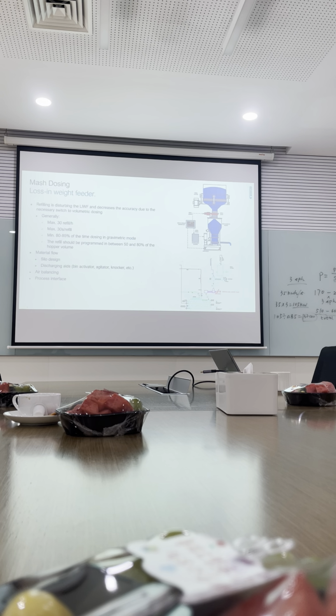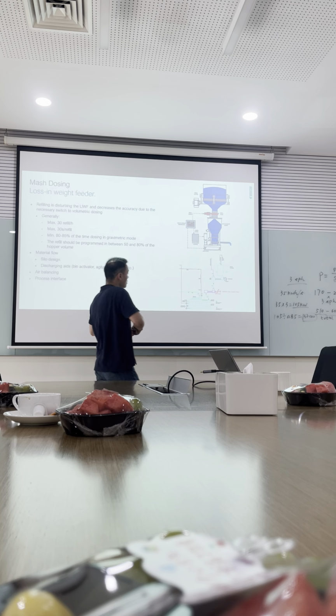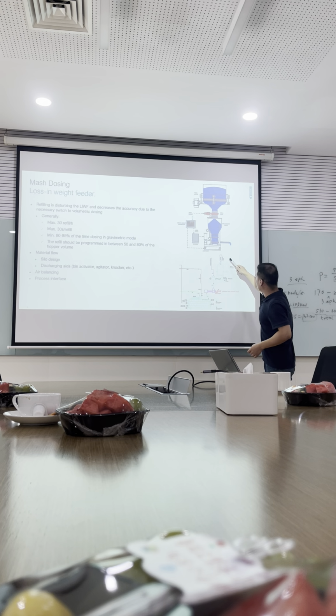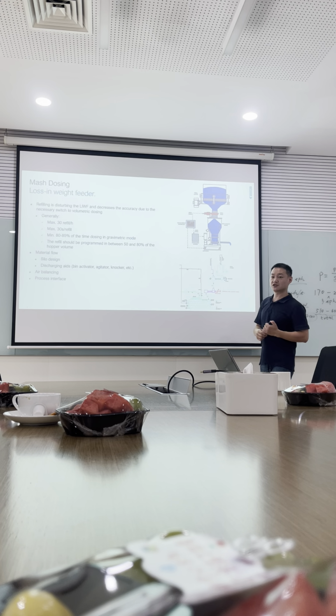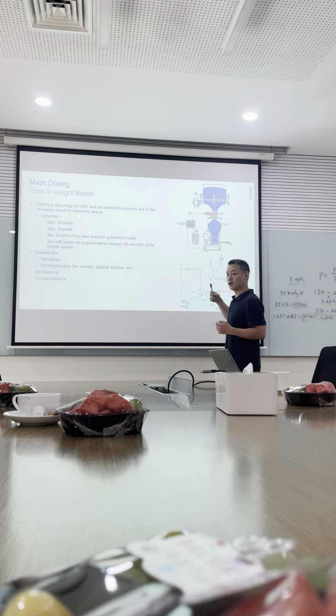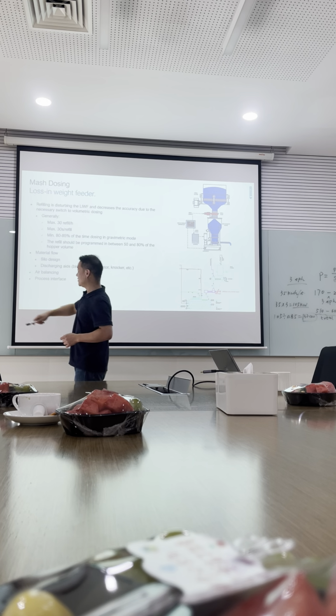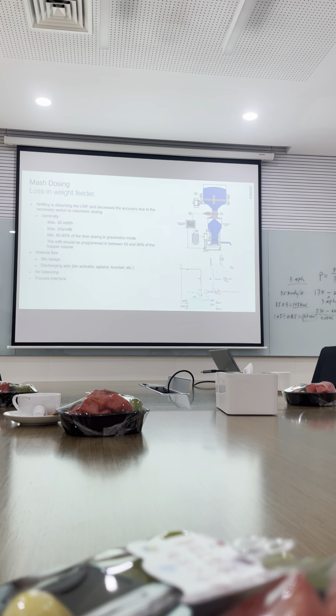Then we know the screw feeder capacity. There is a screw feeder to do the refilling for the hopper, and a lot of times the customer has the wrong capacity. The capacity of the screw feeder to do the refilling is not enough. If the screw feeder capacity is not big enough, then we can't achieve this target. That means the gravimetric dosing time can't be ensured, right?